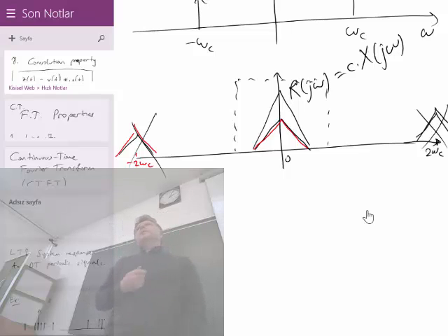Okay, so the last thing that we have seen was this modulation property. We were calling this the modulation property due to a communication system terminology, as you may guess, because it requires multiplication in time versus convolution in frequency. Whatever you do in time domain, you have a counterpart in the frequency domain. For example, if you convolve in the time domain, it means you are multiplying in the frequency domain. And conversely, if you're multiplying in time domain, then you convolve in the frequency domain.